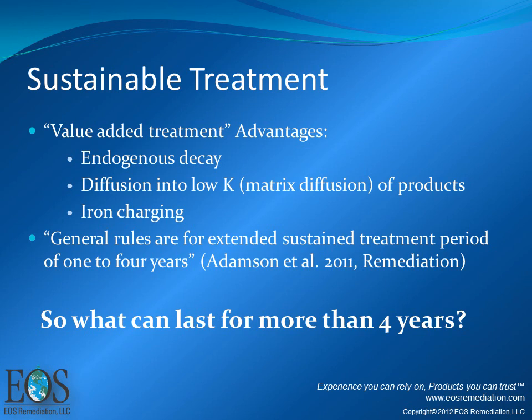Also, you get diffusion of these materials into the low K zones. So just like PCE sorbs into the low K matrix, something like vegetable oil, which is also highly hydrophobic, will dissolve into the low K matrix as well. With strong reducing conditions, you get iron charging, and that prolongs the reducing conditions at your site.